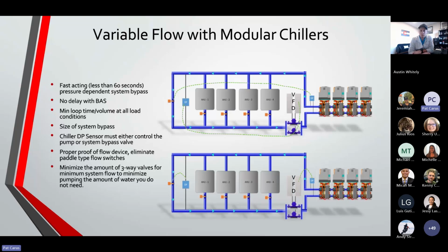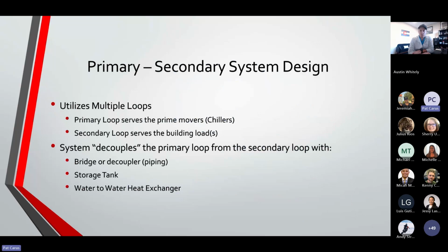We give you all that information so that when the machine is commissioned or started up, whether it's done by a Multistack technician or whether it's done by a representative field service certified technician, we give you that information. A slight difference would be, now that was variable primary, this is primary-secondary, which has multiple loops. We'll also show you the calculations on what the DP requirements are and the minimum flow requirements are.